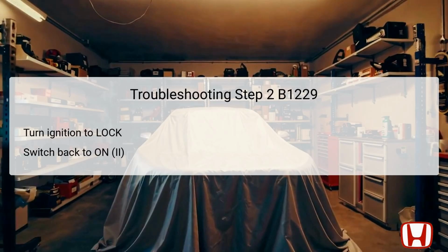The second troubleshooting step involves turning the ignition switch to the lock 0 position and then back to the on 2 position. This process is crucial for ensuring that all systems are adequately reset and initialized before performing further diagnostic functions. By transitioning the ignition through these states, technicians allow the vehicle's onboard systems to refresh and recheck their operational statuses.